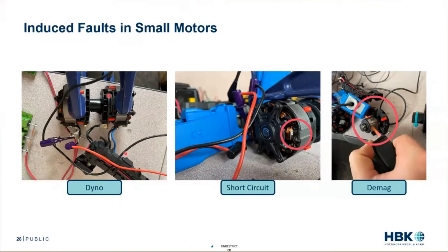I have 2 drill motors, and I just hooked one motor up to a resistive load. So it's kind of like a constant torque dyno. I have the other motor hooked up to my inverter, which is just the trigger of the drill hooked to a battery, and I'm making voltage and current measurements on the 3 phases.